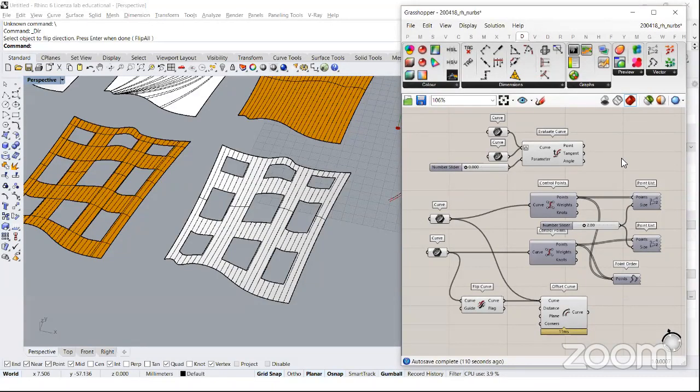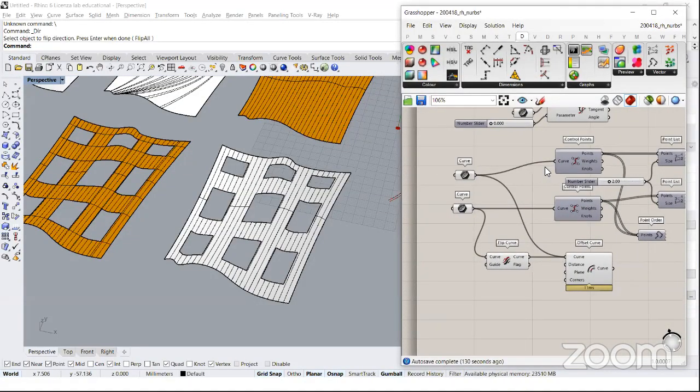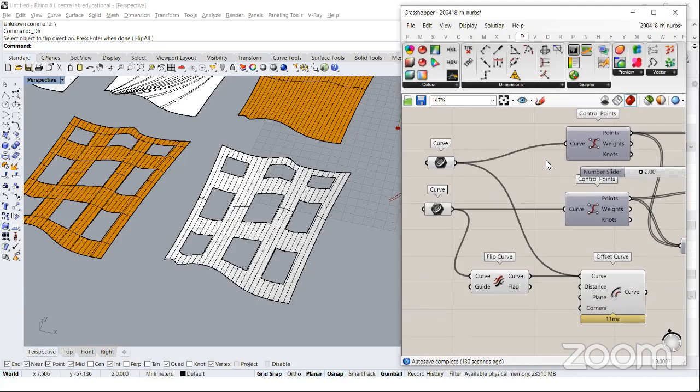As regards whether you would rather reorganize the point order inside the curve list instead of using flip curve: no, flip curve is something that works. If you are in the middle of the definition and you see that there is an opposite direction for one curve, then you might want to flip it instead of going back and reorganizing everything.